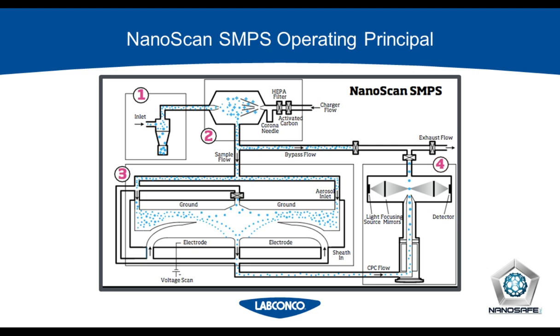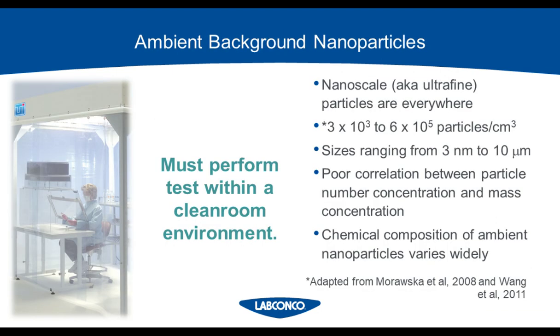This is a little bit different from an ASHRAE 110 gas detection method. I also mentioned troubles with eliminating background noise. In this test, we used silicon dioxide, which is easy to generate and relatively safe, but it is sometimes available in the environment.